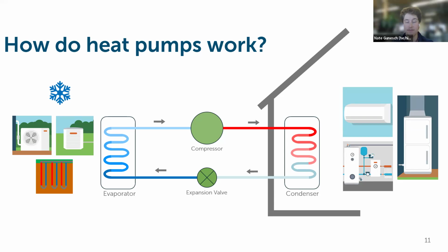I do want to highlight something I mentioned earlier, which is that traditional fuel-fired heating systems have really high temperature distribution. So for example, an old school boiler might distribute water around your house that's 180 or 200 degrees. Boilers are sort of easy to think about because we can generally look at the set point temperature. Furnaces can fluctuate a little bit, but with a boiler, we can see exactly what temperature that water is that's going to be moving around your house.